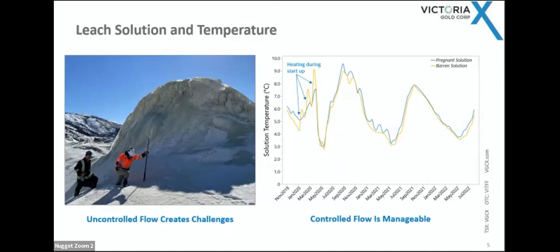We've got just over 12 million BTUs capacity for solution heating. But what we noticed is the solution actually heated up pretty quick, and very shortly, it wasn't necessary to run it. So we were able to turn it off. And you see the seasonality swings where it drops way down here. This is all fresh meltwater infiltrating the heap. And then the temperature rebounds over the year, going up to just over 9. And you can see this seasonal cycle, and it's actually starting to attenuate right now. And I think in probably 2 more years, the heap will be a constant 6 degrees, no matter what.